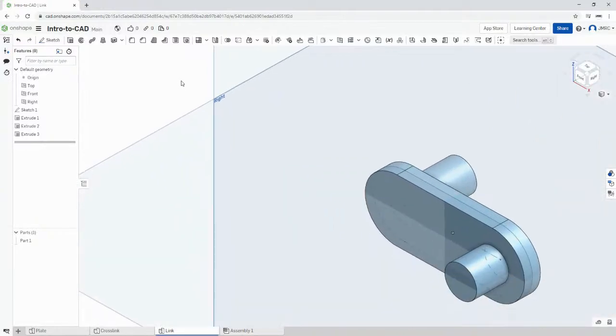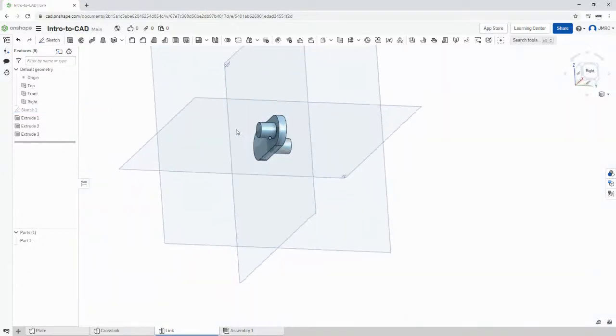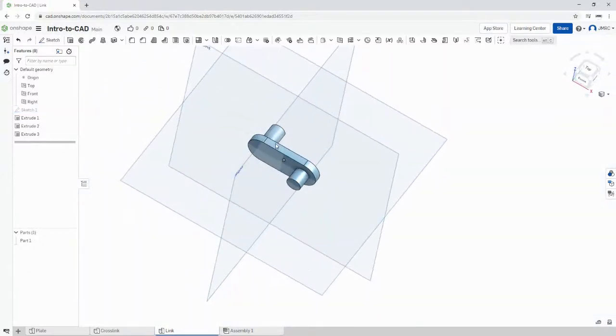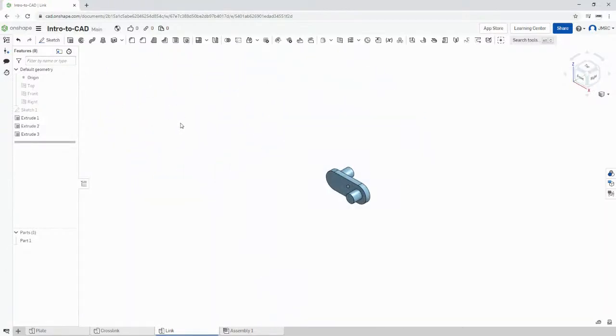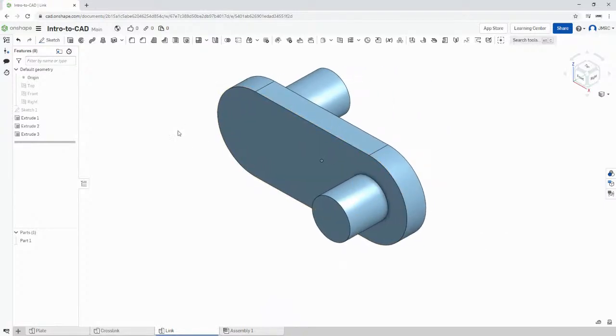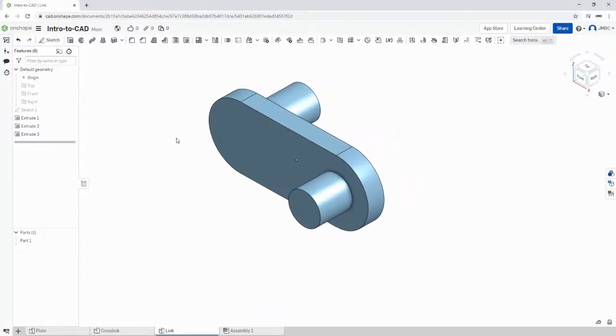Okay, so let's clean things up. I'm going to head back to our sketch 1, and I prefer not seeing this sketch any longer. Selecting this eyeball, turning off that sketch visibility, and hitting P as well to turn off our planes. Yes, and congratulations, we have now created the target 3 parts for this challenge of creating a rotator assembly.